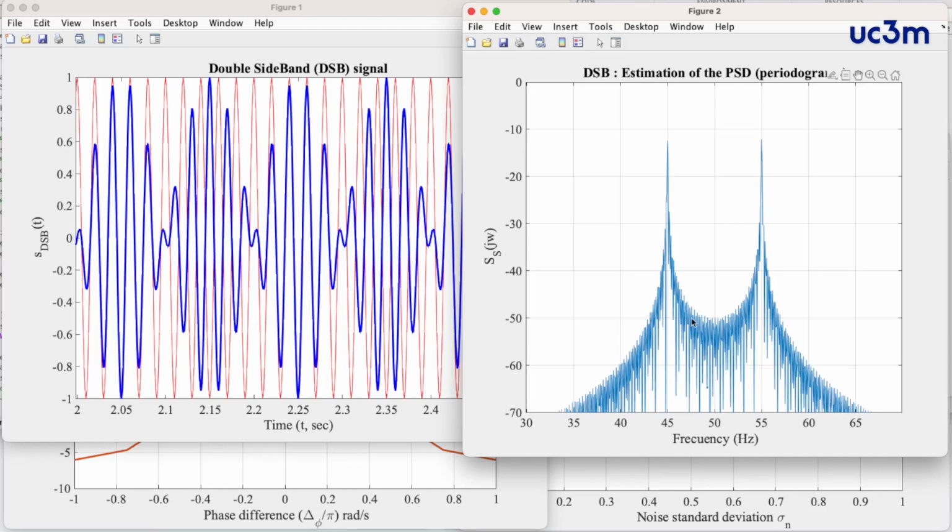The carrier frequency is 50 kHz, and we have the spectrum of the modulating signal, two deltas at -5 and +5 kHz, centered now at the carrier frequency. Carrier frequency is 50, and the deltas are in 55 and 45 respectively.